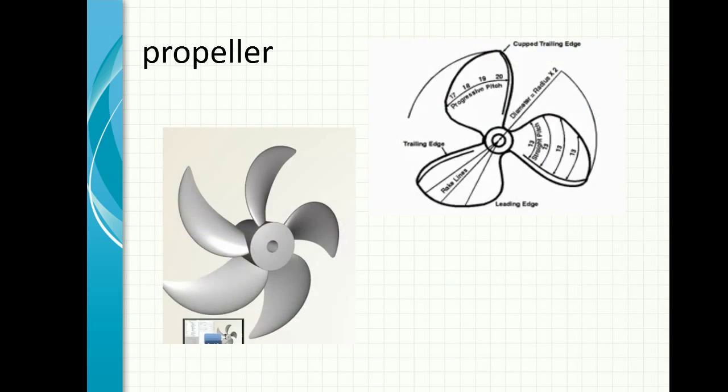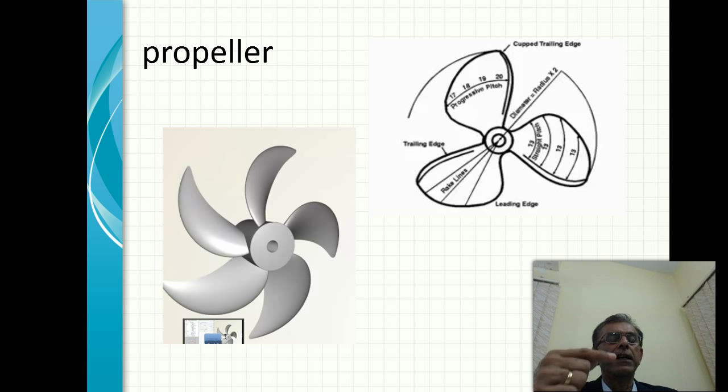The propeller is another complex piece of machinery. In essential principle it is like a screw, but it is quite different because in water it has to produce a thrust. So when a propeller, like an aircraft propeller, rotates at a certain speed and RPM, it produces some thrust, and to achieve that it consumes some torque. Torque is given by the engine, and these have to be matched, and that is another very important aspect of ship design, getting the design point correctly.